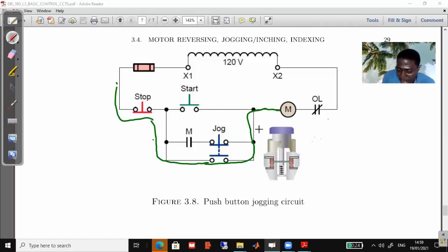Once it is aligned, you couple the motor, because each motor has got a coupling groove or a positioning or aligning groove. So in that groove, when you're coupling a pump, or any other drive, a fan, or anything that is mounted to the motor, you can take advantage of the jogging in terms of coupling. Most of these cases are done because the rotor can be too huge to turn by hand, and you end up using this system of operation, which we call jogging.